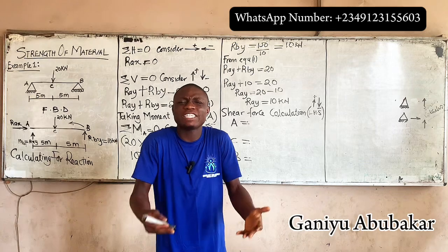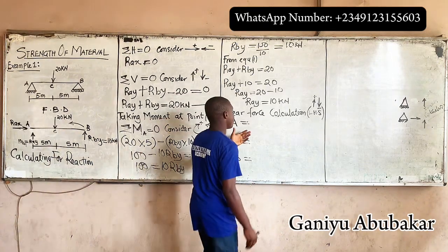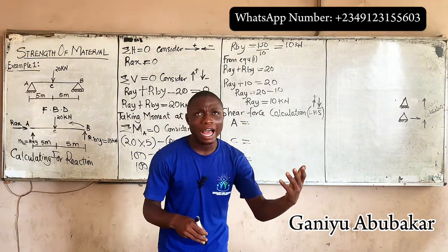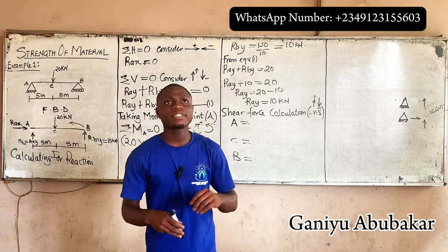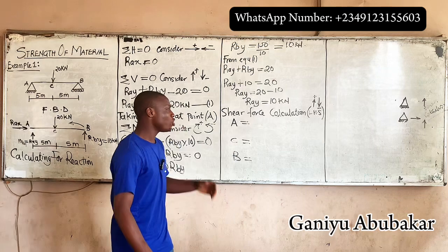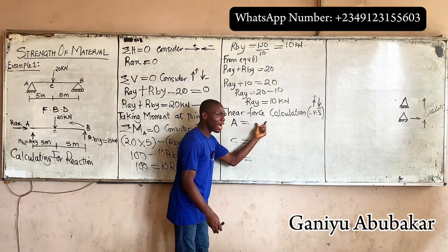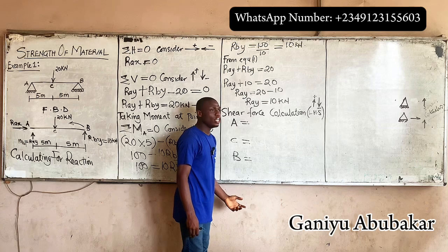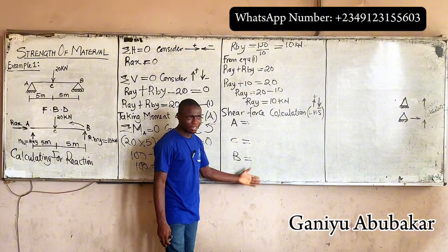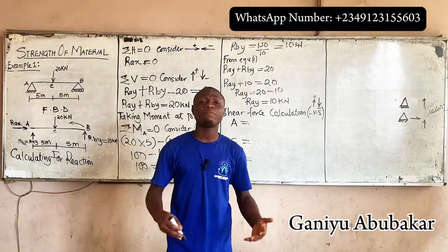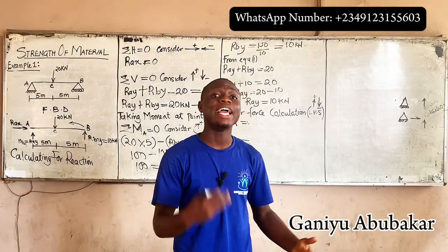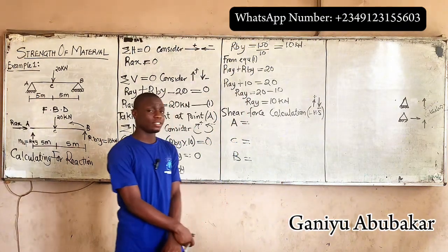Last class we said, for shear force, it always starts with a number and must always end with 0. So in the case of shear force, if you have a value here at the end, you are wrong. Bear in mind that shear force starts with 0 and ends with 0. Let's do this right.